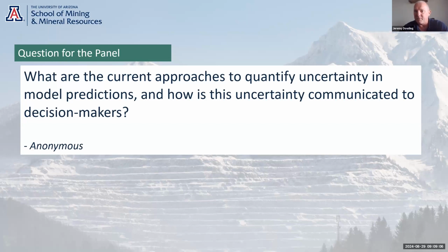But then when the slope's implemented, the wells don't happen and the drains don't happen. And for that reason, the pore pressures are vastly different to what was predicted and what was assumed in the analysis. And that creates a much more significant deviation in the pore pressure regime in reality compared to the classic kind of uncertainties in the hydrogeological model and its parameters, and that is often overlooked.